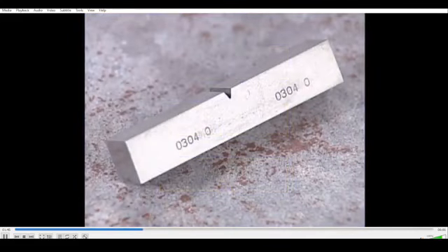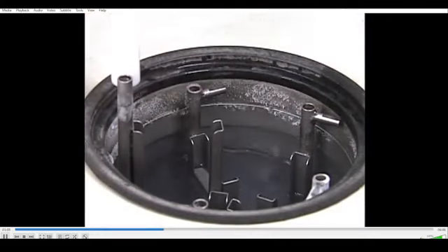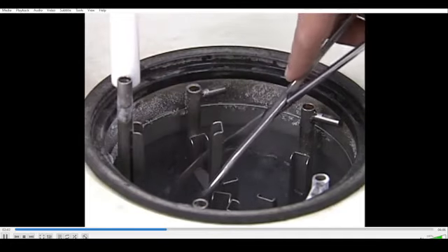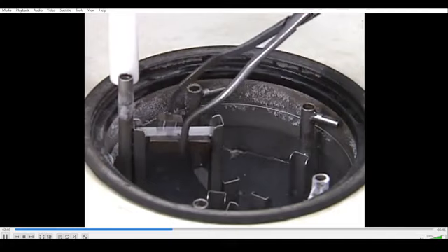Once the required number of specimens has been machined to procedure specifications, they are stamped for identification. Both ends should be stamped so that broken halves can be matched and evaluated. The test is begun by cooling the specimens. Methanol and liquid nitrogen are sometimes used in a refrigerated bath for this purpose.